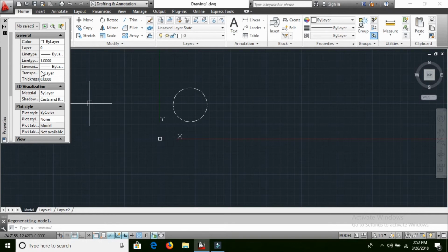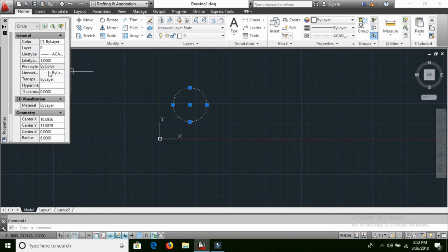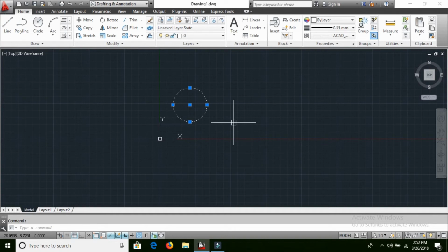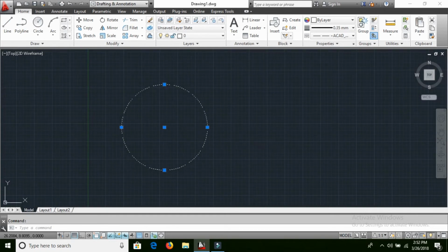And the next one is line weight. See, friends, the line weight is also very simple. We select this object, and I'm going to apply the line weight to this particular object. So I select this weight. But here we can see, friends, that the line weight is not showing on the selected object. We have applied the line weight to the object, but we are not seeing it. Why? Because in the status bar we have the show/hide line weight option. We need to turn it on. When you turn it on, we can see it. Otherwise we can't.